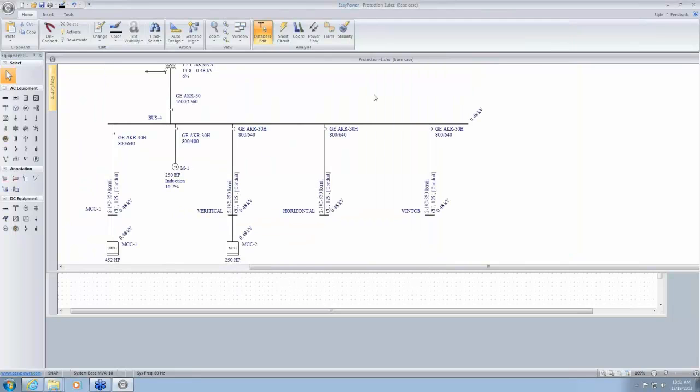There are some manufacturers that have devices that quickly extinguish the arc. For example, the arc fault device, which is pretty much an arc chamber, where they have an internal short circuit that reduces the voltage on the bus and therefore extinguishes the arc because the voltage is not adequate to sustain the arc.